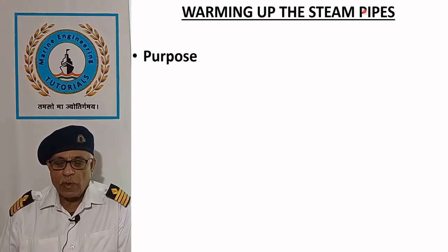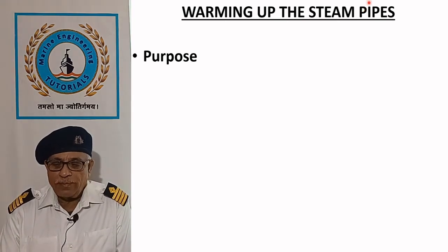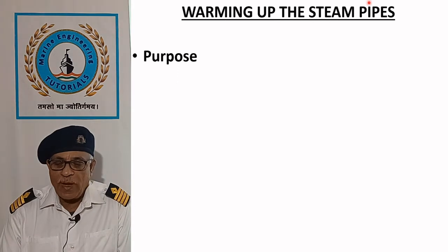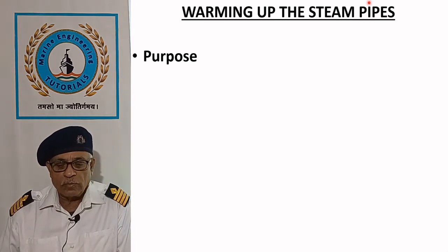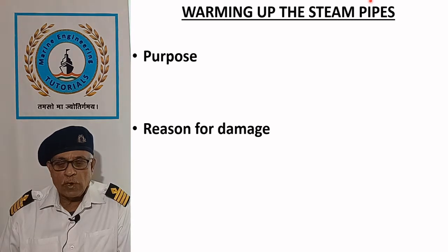Purpose. It is necessary to warm up the steam pipe before admitting steam in order to prevent their damage due to thermal distortion and water hammer. Reason for the damage.